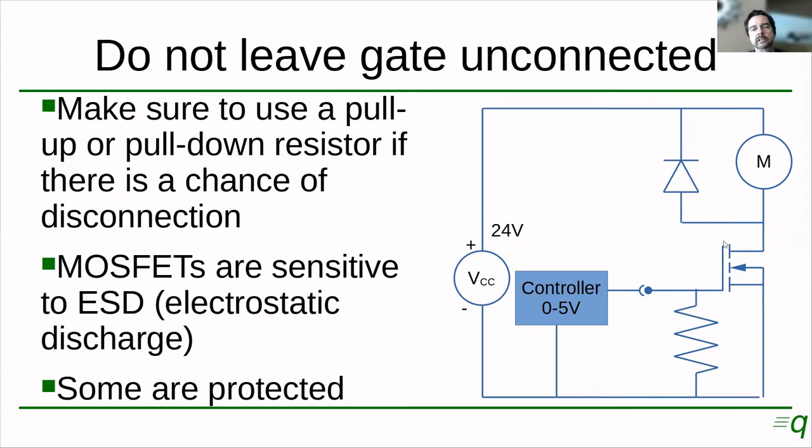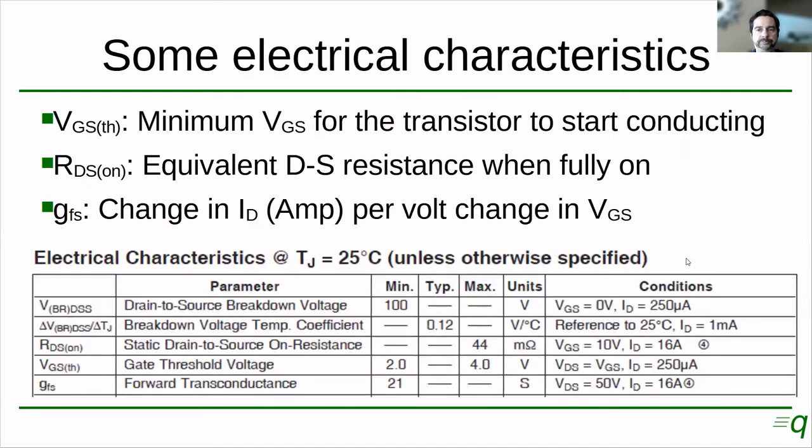Once they are inserted in the circuit, there are different paths for any possible electrostatic discharge to flow, and that will help somehow protect the MOSFET. But it's still always a good practice to ground yourself when working with circuits to avoid electrostatic discharge.